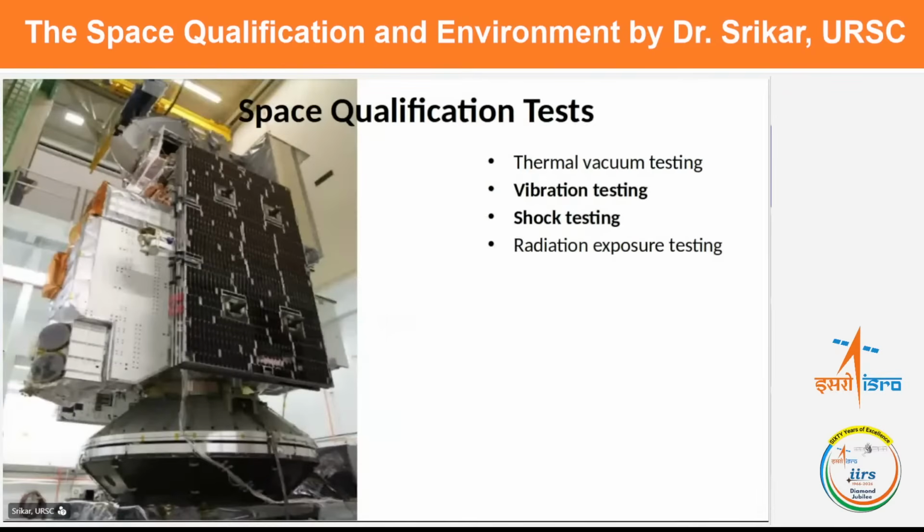And the second one is the mechanical aspect. As I said, there are a lot of mechanical loads that the spacecraft will have to take during the launch. So for that, we do vibration and shock testing. Here, the picture shows a spacecraft mounted on a vibration fixture, and it will be vibrated based on the levels that we expect.